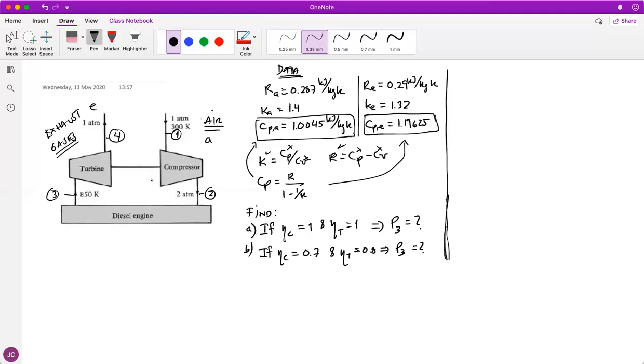I don't know if I'm going to solve it directly by doing that, but this is my way to work when I'm having this type of problems regarding ideal gases and isentropic or not isentropic turbines and compressors, okay? So I'm going to start by doing the process that goes from 1 to 2, but if the process was isentropic. This little s as a sub-index over here means that I'm doing the isentropic process. So the first exercise is telling me, yeah, it's isentropic. Okay, I'm saying fine, but it doesn't really matter. I'm going to use this same data, this same calculation that I'm doing here.